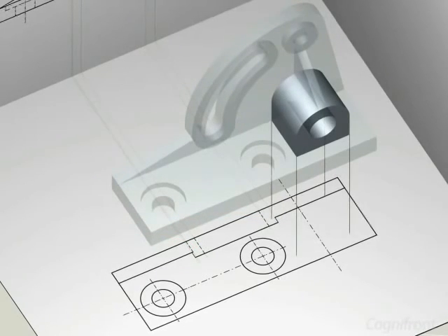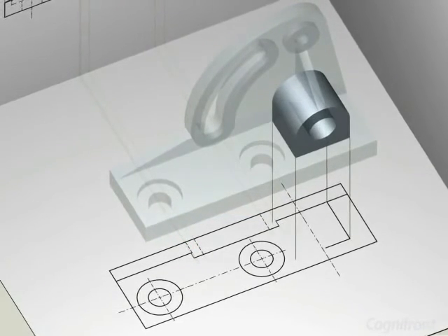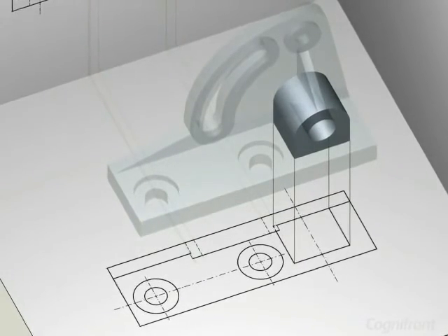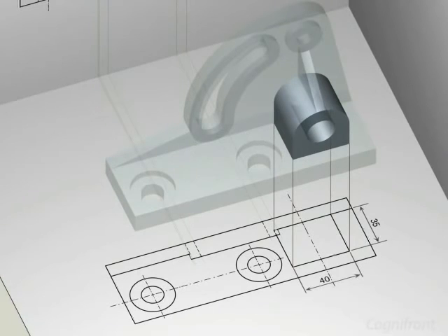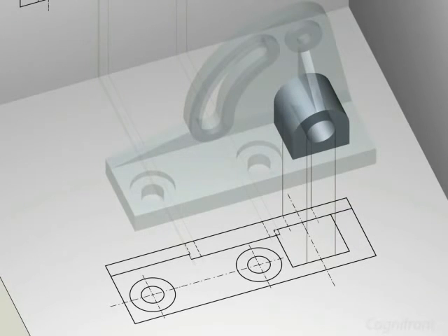Next, project semi-cylindrical extrusion. It is represented as a rectangle of 35 mm by 40 mm. Don't forget hidden lines for the 20 mm hole in it. Observe this acute overlap of slot with this semi-cylindrical portion as seen in the top view.